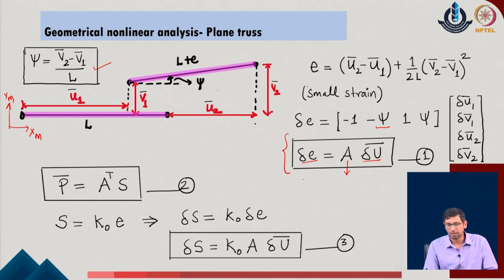So, we can understand that this overall expression is a function of displacement, or one can also write in a general form that E, the change in the length of the member, is equal to a function of the displacement. This identifies one basic idea: any change in the length of the system is no longer a constant value, but depends upon the amount of the nodal displacements of the given system.